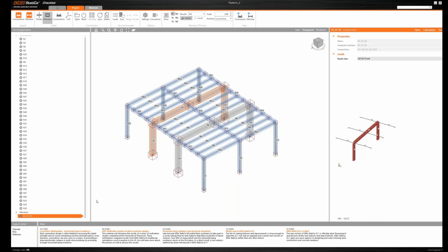To make sure that these sub-models can replicate the calculated behaviors that reflect the limit states, we must recreate their boundary conditions to match the ones of the global analysis model. In this application, besides the geometry, we also import the loads and guarantee an accurate representation of all the boundary conditions.